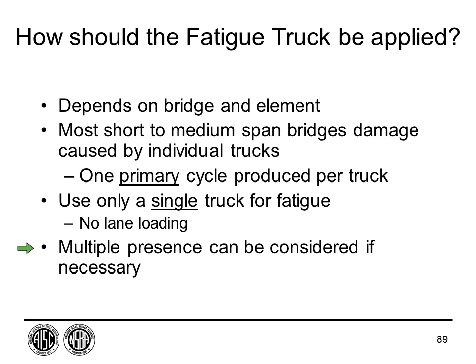Now I will caution you, as a designer, if you have reason to believe that the fatigue truck should be in more than one lane, let's say it's a bridge that's going in and out of a quarry, and you know that there's a lot more loading, then you should consider multiple presence. But that's something as a designer you would have to think through and make sure that you need to do that.